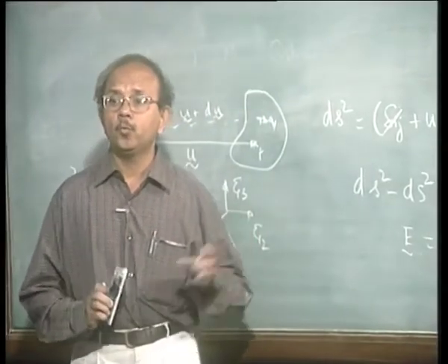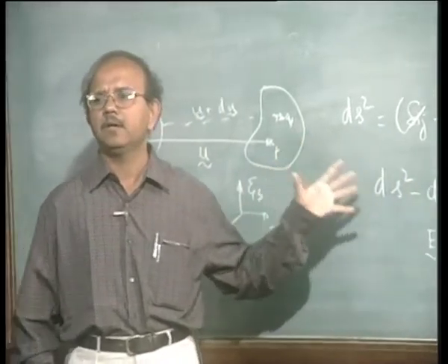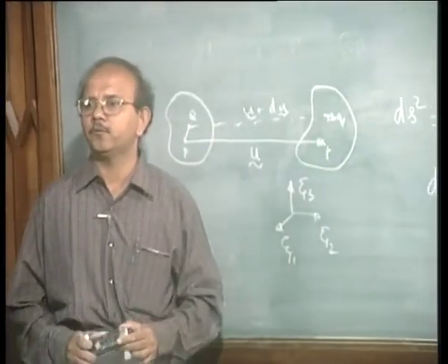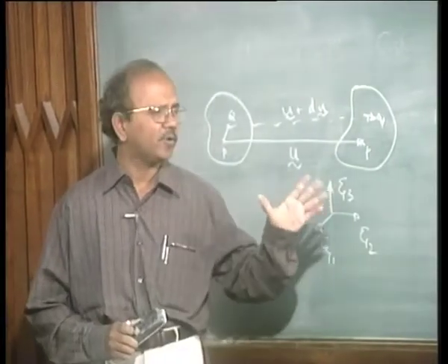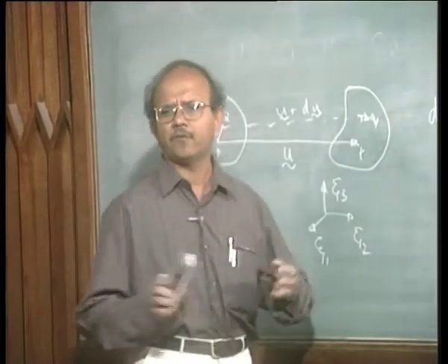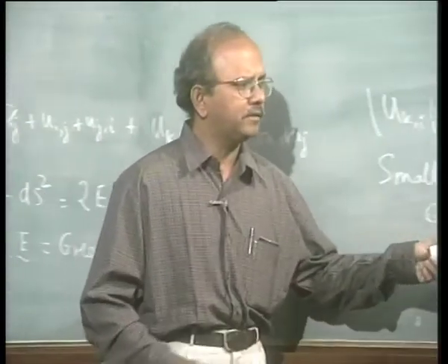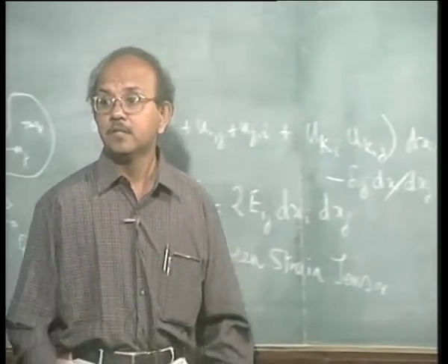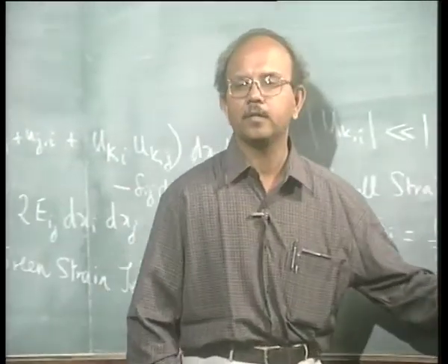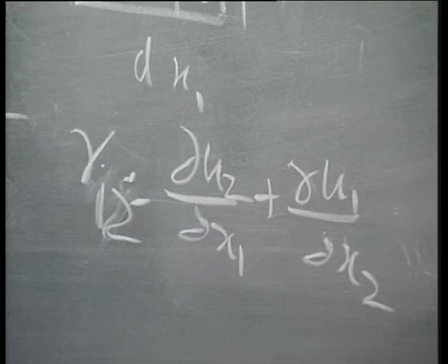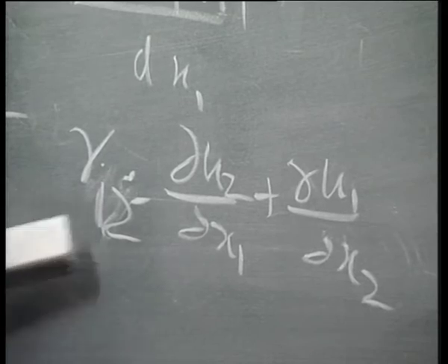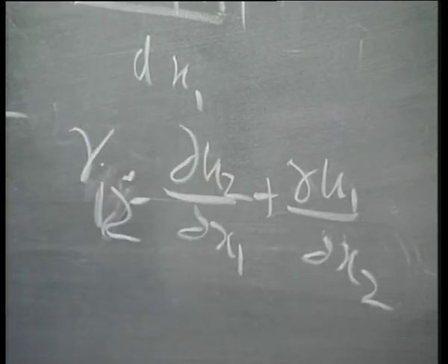So, though we defined it very tortuously, if you want to call it that, I know that you have to follow really every step. I think we are not very far off from what we know. We have put that nicely down in a mathematical sense. This equation is very crucial for finite element analysis. Why? Basically because this gives me a relationship between strain on one hand and displacement on the other hand. Remember, go back to our finite element days, what we did about 4 or 5 classes back.